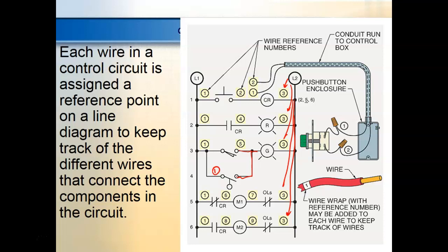But every time I've taught this class, I want y'all to make me a liar. Every time I've taught this class, somebody has numbered every line. Somebody has given light bulbs contact numbers, right? Somebody has put a jumper all the way over here, down here, and down here, even though the two terminals are outside each other. Now, electrically, that's okay. It's just that if you were an electrician bidding on a job, somebody would underbid you, because you'd be using all this wire, and this guy over here would be using a lot less doing the same job.